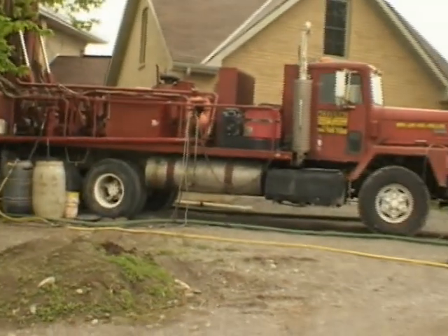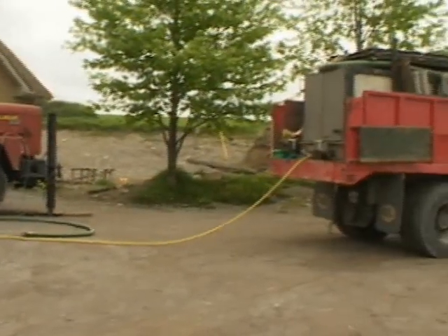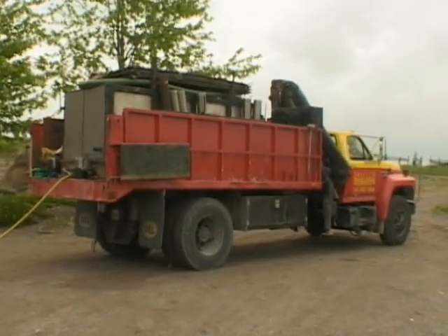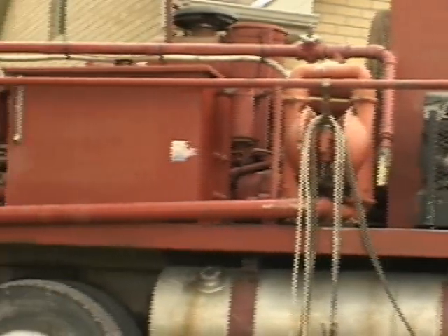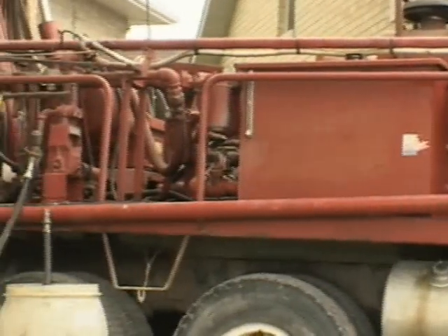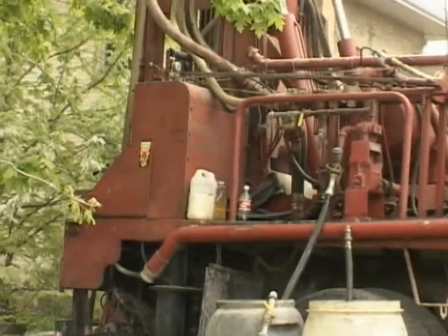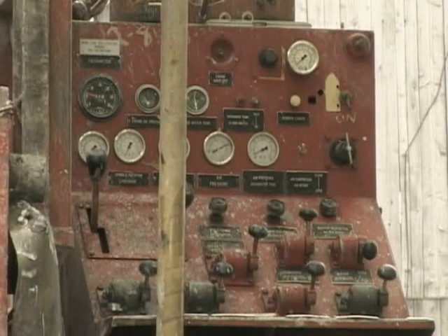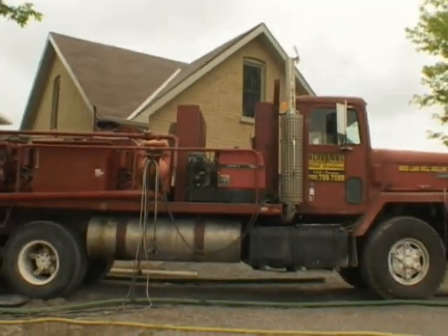Support equipment for this drilling system includes a support truck with a large water reserve on board. In addition to welding equipment, the rig also includes an air compressor, which is used to power the casing driver, as well as act as a flushing media. The truck's engine is used to power the rig through a transfer case. All systems are hydraulically powered, with the exception of the air-driven casing driver. 2 technicians are required to operate this drilling system.